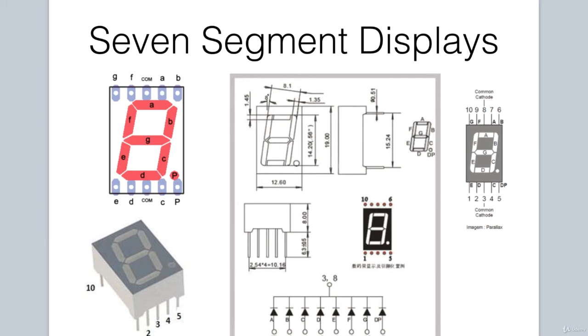Let's first address how 7-segment displays work. If you look at the schematic for a 7-segment display, you will see that each segment, or individual piece that has to light up to display a part of the final result, has a letter and a corresponding pin that is associated with it.